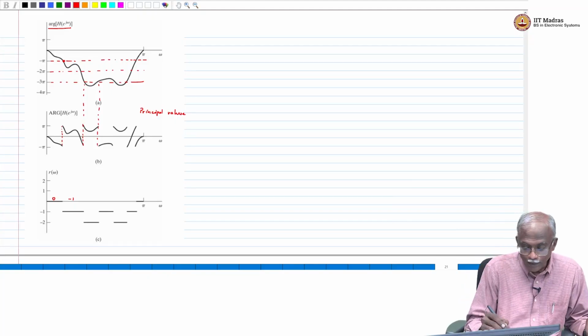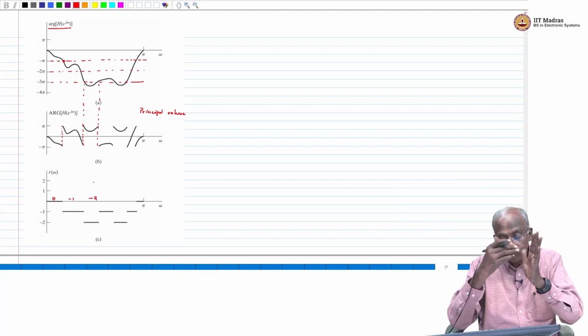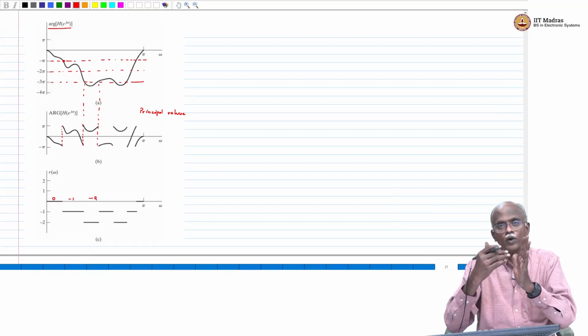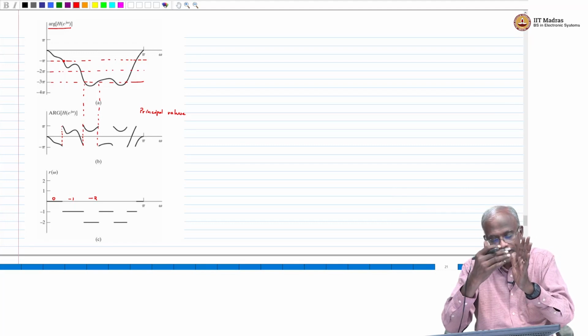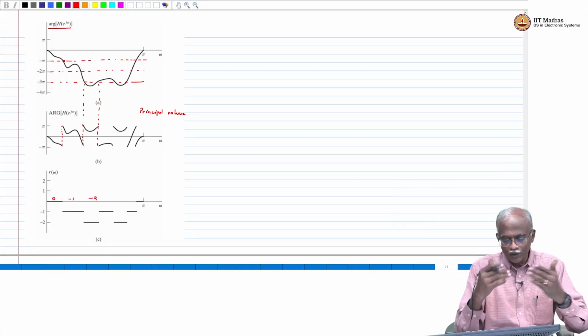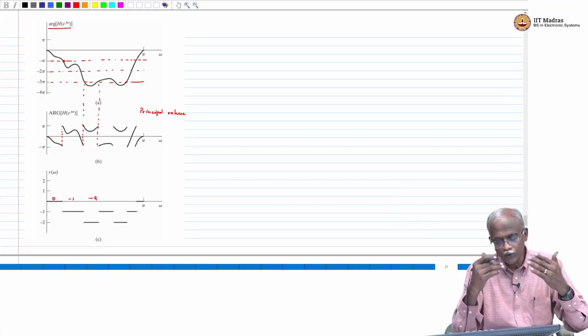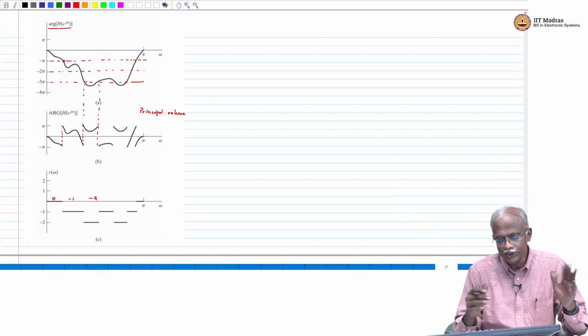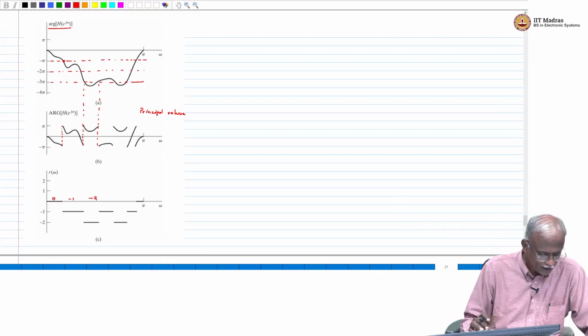And in the third part, you have to subtract minus 4 pi, right, minus 2 times 2 pi, and so that is what will tell you the true phase. So depending on where you are, you can add or subtract multiples of 2 pi and get back the original response, or get back the true phase.